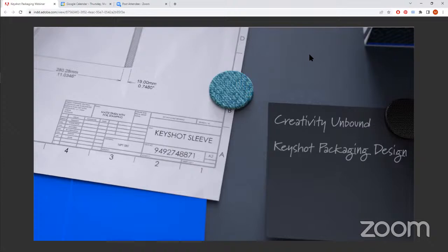I'll add in some noise. And if you're doing a fine folding carton, it's going to look kind of similar. As far as corrugate, I think Polygon does a really good job. Or sometimes I'll take photos and use them as reference, where I'll add wrinkles into it, either in Photoshop or in KeyShot. I'll use a bump map and add in those wrinkles.